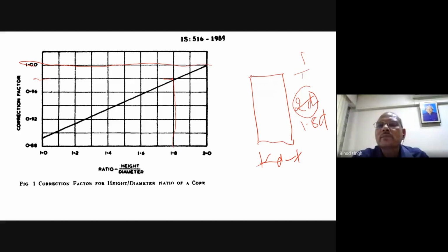Suppose this has an undulated surface. So you have to cut this undulated surface in a saw machine and put a cap. Make it smooth. There is a method of doing that. It should be very much vertical in nature, not undulated. Otherwise, you will not get the proper result. So that you have to go for the capping.